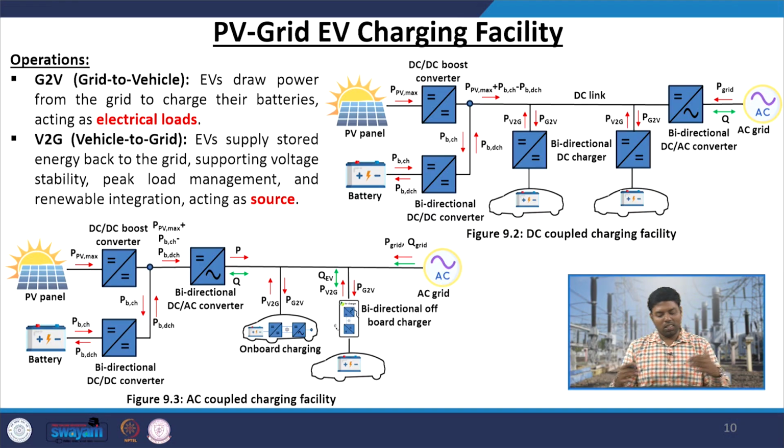So, it is a similar arrangement to what we have studied, how we can connect a battery with the electric AC grid. The first one is the DC link: you can connect a bidirectional DC-DC converter if you have off-board charging. So, you do not need an AC-DC conversion, you just connect it with the DC-DC conversion and you can take power or supply power.